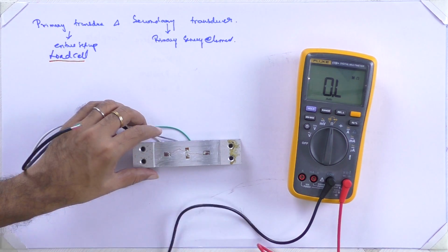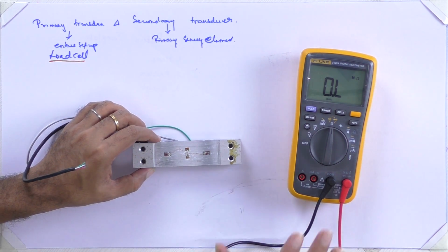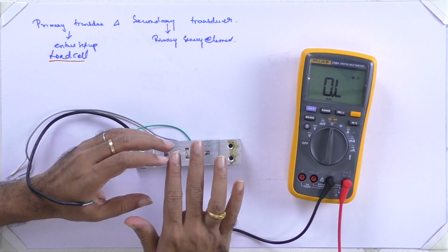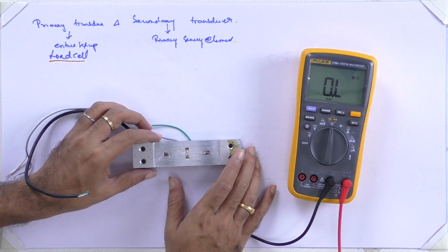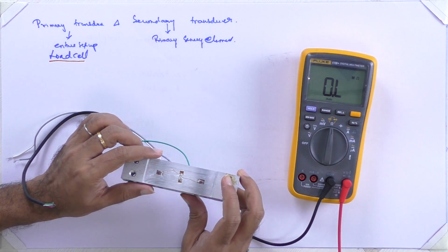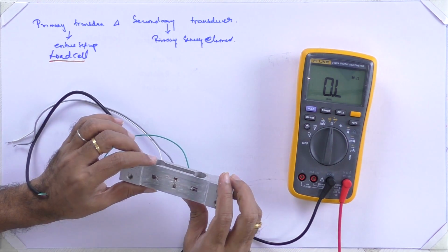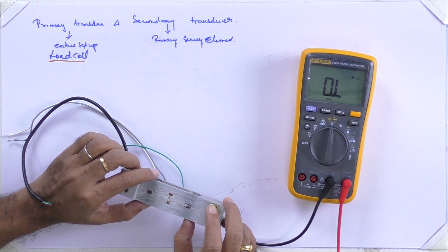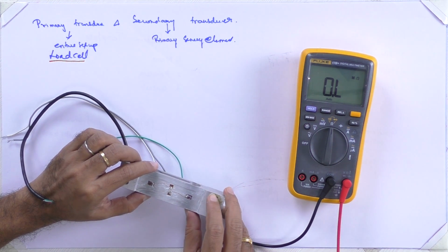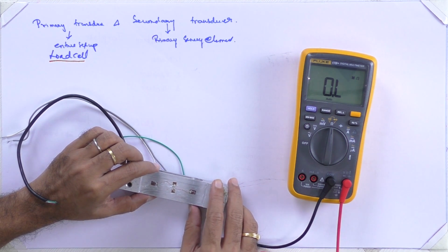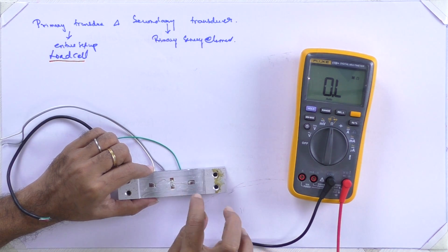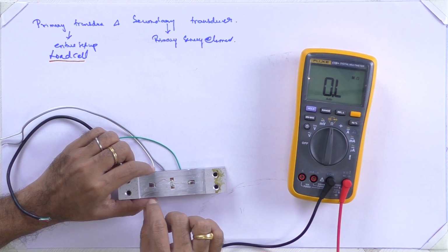Like this, inside this load cell they have utilized all the primary sensing elements, the strain gauges, as 350 ohm transducers, and they have constructed a full bridge circuit. What is this full bridge circuit? You have to recall a Wheatstone's bridge, and inside a Wheatstone's bridge, in each arm, one single primary sensing element is connected, and the output is taken.